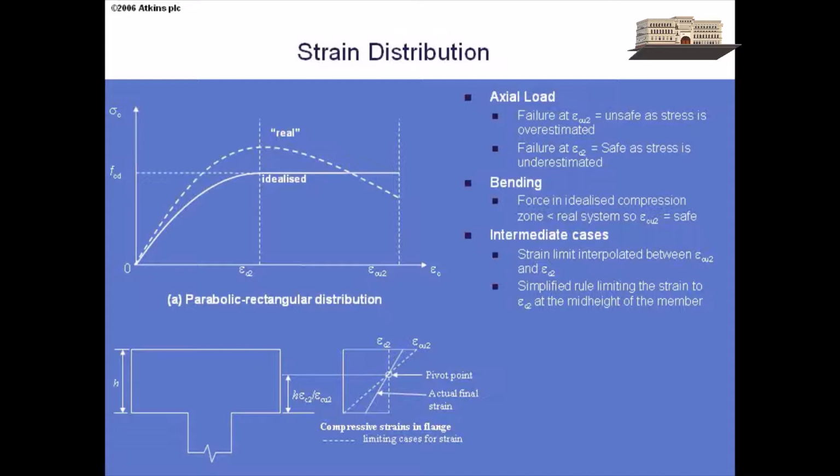So this makes life difficult. We didn't worry about this previously in the good old-fashioned BS 8110. What it actually says is if you have sections which are in overall compression with some bending, or even if you have flange outstands which are wholly in compression with some bending, then you have to work to a new stress limit. And this picture is trying to show what you have to work through.